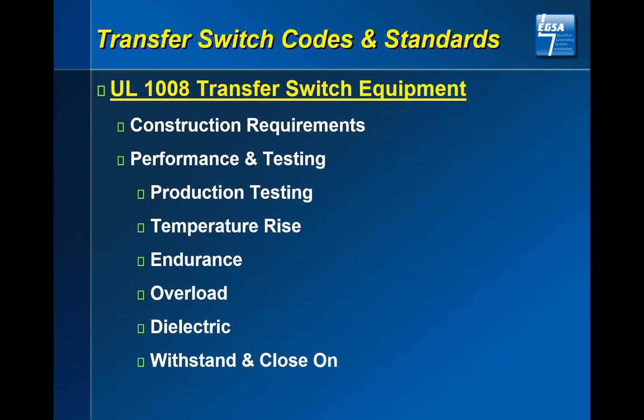I'll give you the preface to that. The transfer switch may be a 600 amp rated transfer switch. That's what's going to pass through it typically. However, if there is a short downstream, depending on how close you are to the utility transformer or such, you may have in excess of 30 to 40 to 50,000 amps of fault current that will flow through that switch instantaneously.